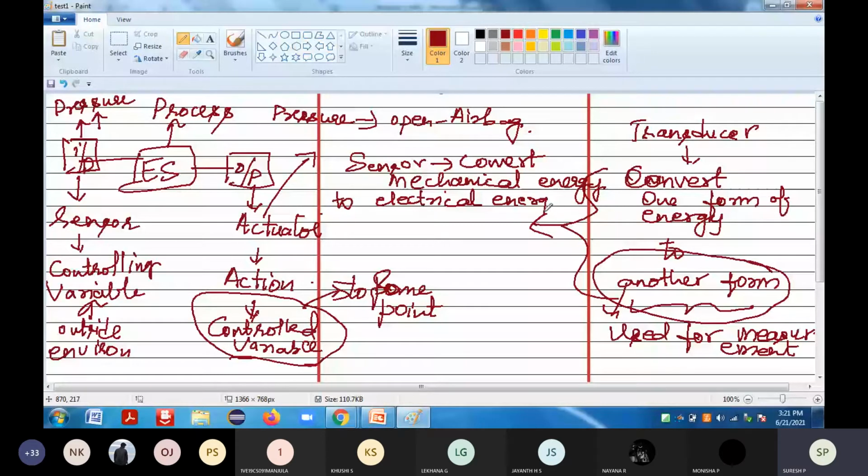Depending upon the corresponding elements to be on, that particular LED should be on. If it is for 1, B and C will be on. That means B will be 1, C will be 1, others will be 0. Similarly, if I want 2, A will be on, B will be on, C off, D is on, E is off, then G is on. So F is 0, E is 1, D is 1, C is 0, B is 1. Now this has to be converted to a hexadecimal value, and it will be represented.